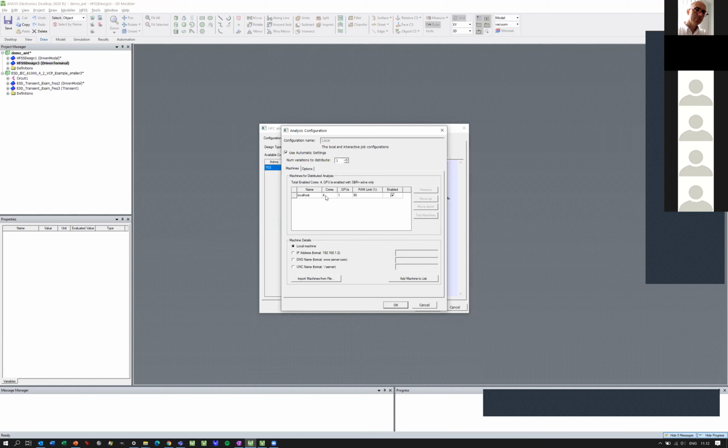I think the default is 4, but because I'm using my laptop with more CPU cores, I'm using 8, and use as much memory as possible. That's always required. My laptop has 32 gigabytes, and it's already not a lot for simulations. Many simulation software packages require a lot of memory. Heavy simulations require 2 terabytes, and typically in that case, we use a cloud system. Small simulations up to 500 gigabytes we can do on a workstation. More heavy simulations, we have to go to the cloud.